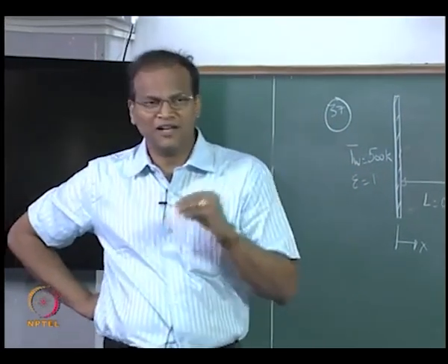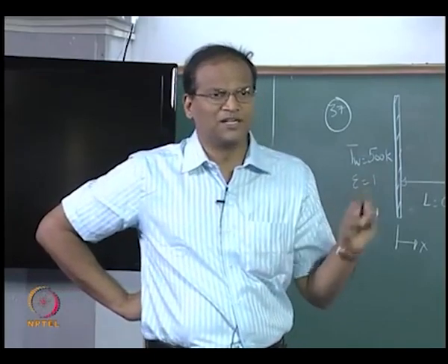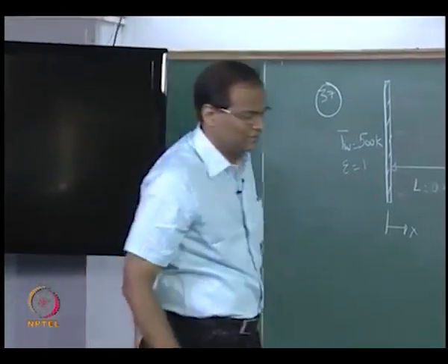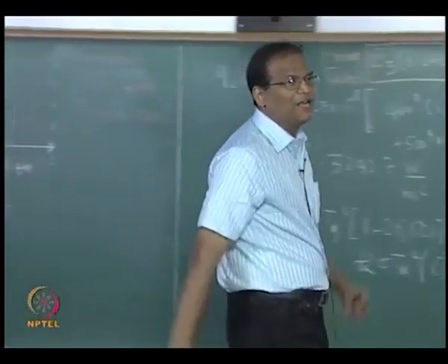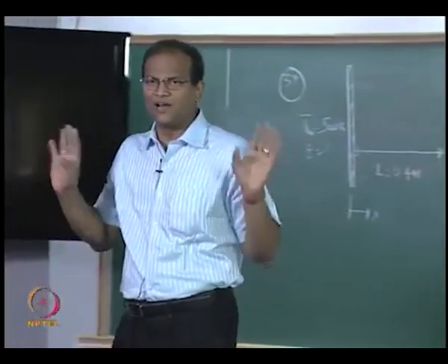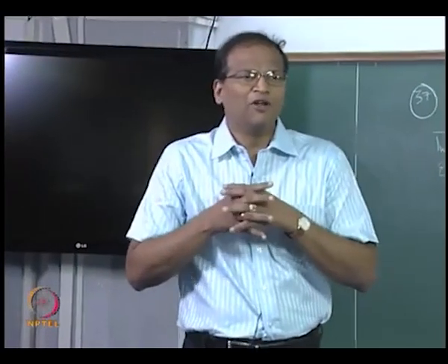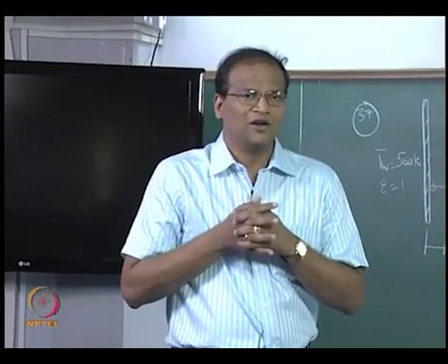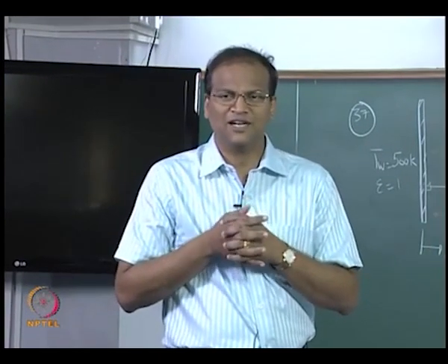CO2 and H2O, people have done experiments at 1 atmosphere pressure, and they have given the charts, which incidentally are given in pages 2, 3, 4 of the handout. So there is a recipe available. We'll look at the recipe in the next class, and then using that you can calculate. But beyond that, if it is other pressures or other things, we'll have to solve the spectral radiative transfer equation and get all this.